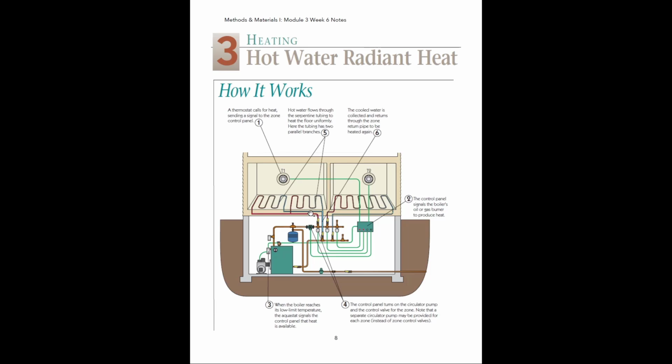However, once they reach the rooms up here, they're not being distributed to a unit, like the radiator or the baseboard heater. They're instead being distributed to a series of pipes, which are laid out in a serpentine pattern. And as these pipes heat up with the warm water, they're going to be radiating that heat inside of them to the subfloor and then all the way up through into the air above.